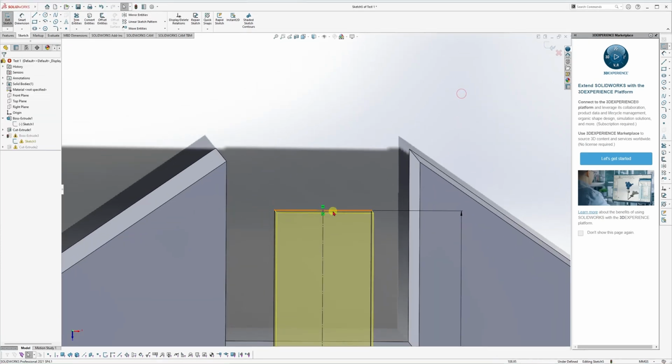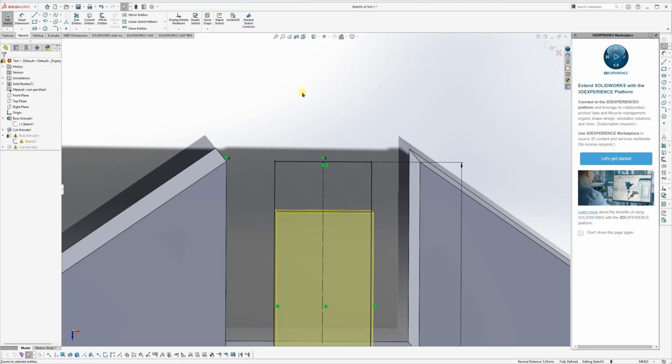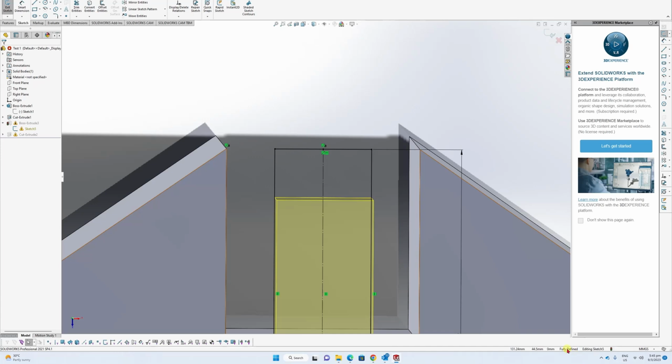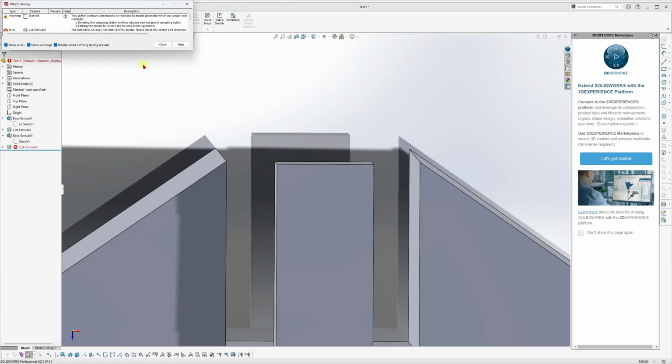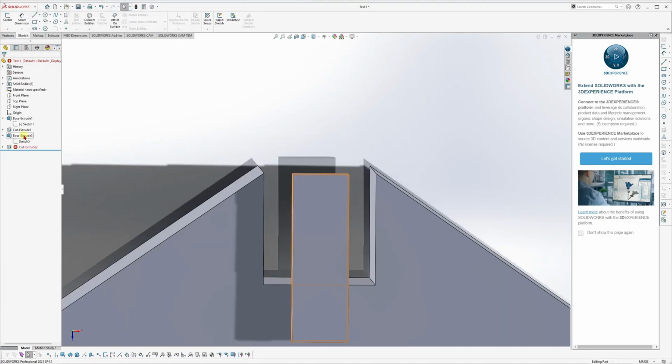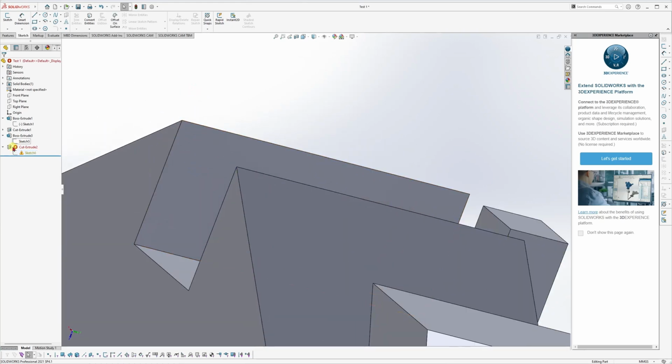So what I'm going to do is click this, and let's say I want to align with this one. So I'm going to make it coincident, meaning this line and that point will coincide, meaning in one line. Now I'm fully defined again, and if I accept, continue, this one is already solved. Now I still have another error here. So what's this error?